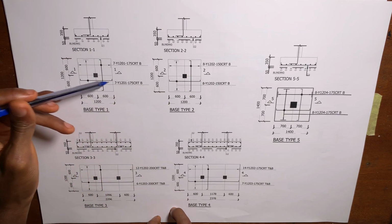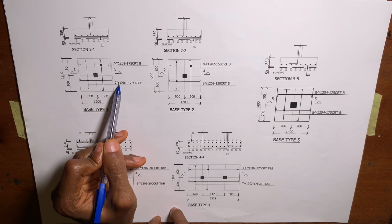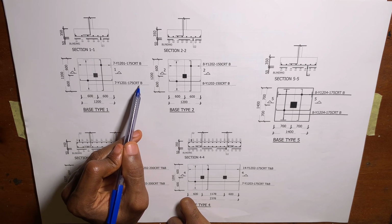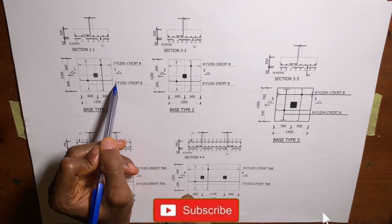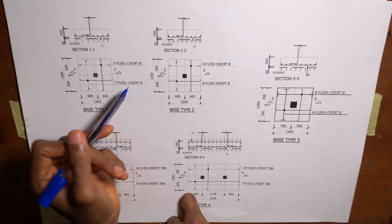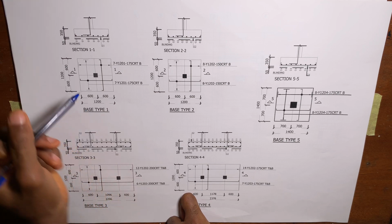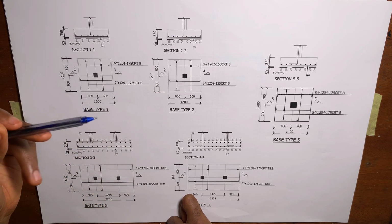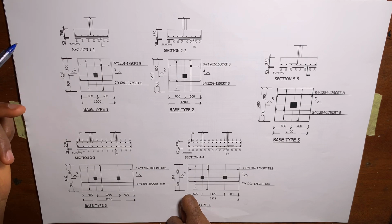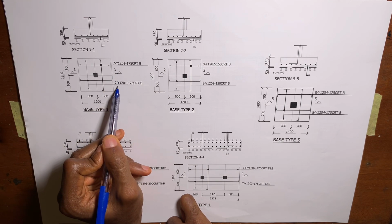Similarly, for the horizontal bar, which is this, you can see it says 7Y12. That's 7 number of Y12 reinforcement. This is bar 1, 175 center to center, bottom bar. So you can see that the information we have here for the vertical and the horizontal reinforcement is the same. Why? Because the length is 1200 and the width is 1200. Since we are using the same type of reinforcement and the same center to center spacing for both the length and the width, the numbers are going to be the same. So both the vertical and the horizontal for base type 1 is 7 in number.